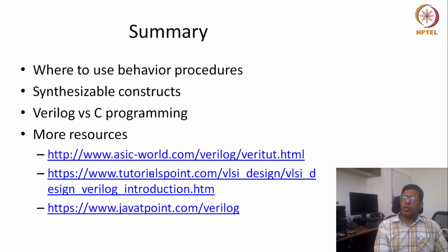For combinational logic also we can use the behavior model, but during synthesis we are not sure what we are getting. And another big catch is that whenever we are using the behavior model, we tend to write like a C program.